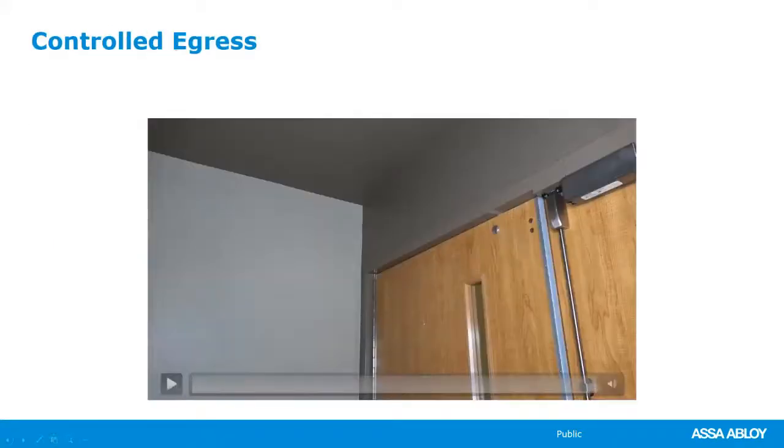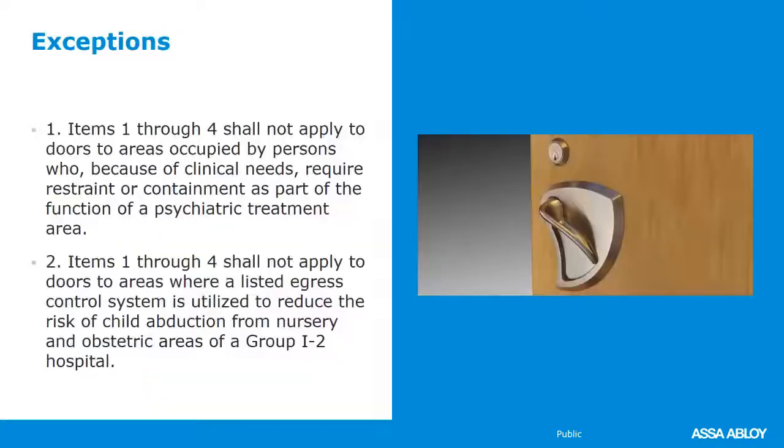So again, the requirements are a fail-safe lock tied into the fire alarm system, so on actuation of the fire or smoke detection system it will drop power, and all clinical staff must carry the key or credential. In this case, it would be the badge. There are some exceptions to this.